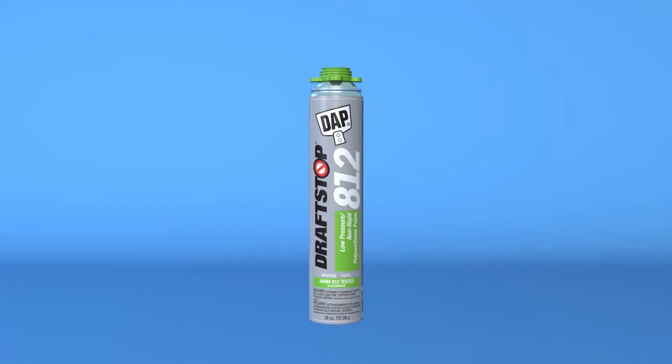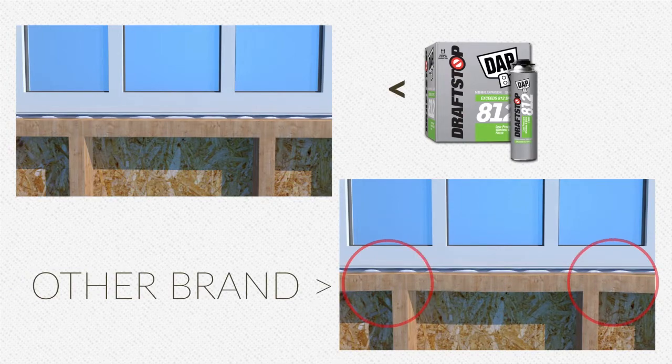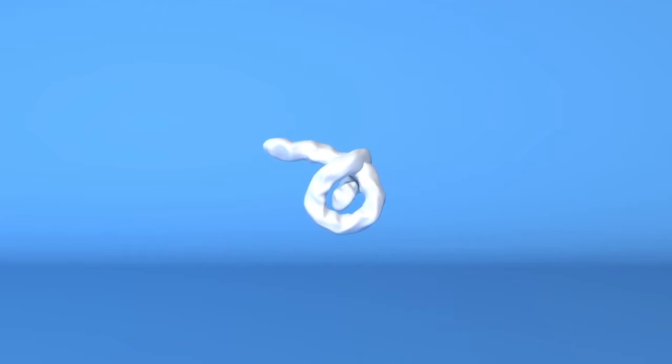Draft Stop 812 offers unique benefits compared to other foam sealants. It will not warp or bow window frames. It is highly flexible, with up to 30% joint movement capability. It is closed cell and will not absorb water.